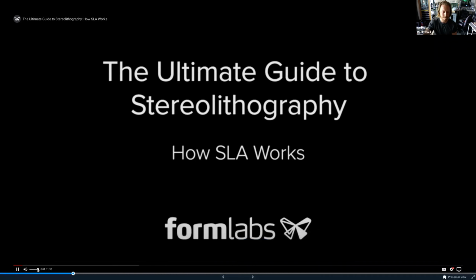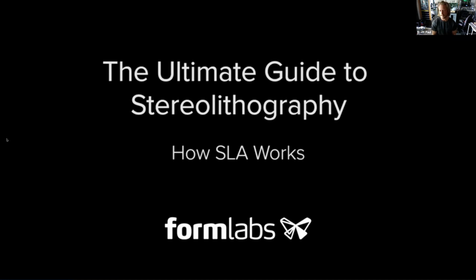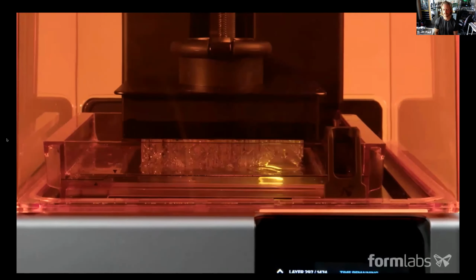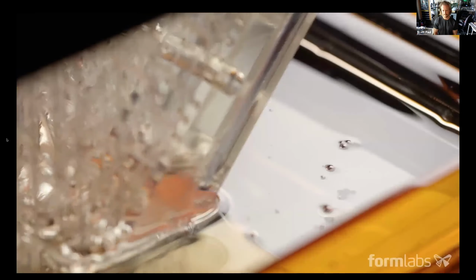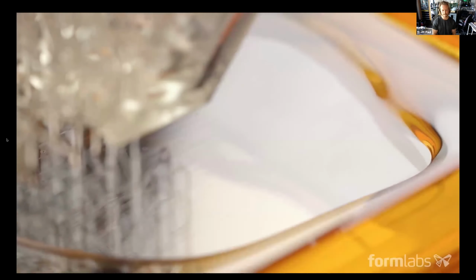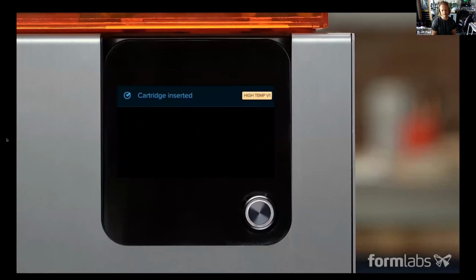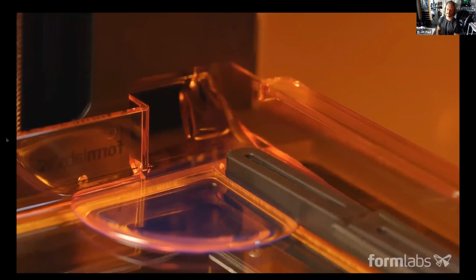3D printing technologies create solid parts from 3D models layer by layer. Among them is SLA. SLA stands for Stereolithography, a 3D printing process that uses a UV laser to cure liquid resin into hardened plastic. Upside down or inverted stereolithography is the most common SLA system. Depending on the machine, resin is either poured into a tank by a user or dispensed automatically from a cartridge.